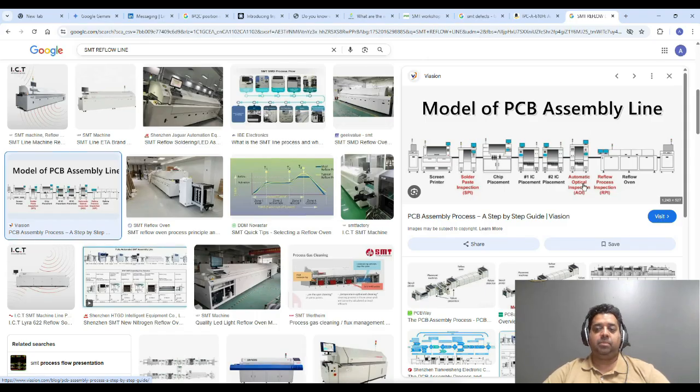Same thing here, automatic inspection. So you have the solder paste, the board comes to pick and place with the solder paste, and then you do an AOI after pick and place. If the components placed are not correct, you can go back and repopulate the boards, or you can do it by hand if there's an error of one or two components, or you can completely remove all the components and redo it. There are a lot of things you can do. Again, the idea here is that you don't waste a board. So if you had 100 boards and this was the first board you were playing with, you can still keep fixing it up and using it.